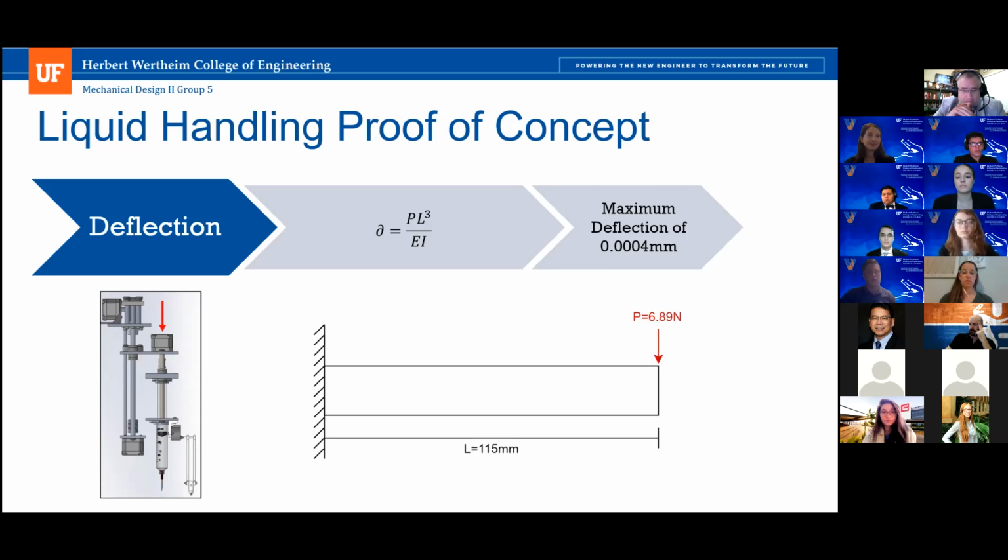Okay. And while we have this picture up on the screen, we've got a big old cantilever beam, a complicated cantilever beam, hanging off of your motion system here. I don't remember seeing a vibration analysis with your shaker motors going. Is that a concern, that you're going to excite any natural frequencies here? We haven't done a calculation to confirm that, but we don't expect it, at least. But that might be a good thing to include in our final design report. Yeah, I'd suggest doing that.